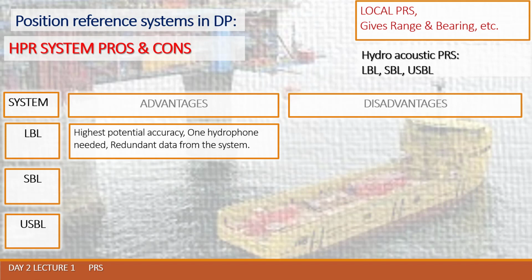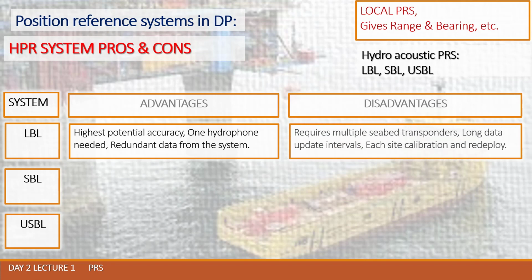But there are some disadvantages for long baseline. It requires multiple seabed transponders, long data update intervals, and each site calibration and redeploy is needed. Expensive maintenance, expensive beacon installation, and so on.